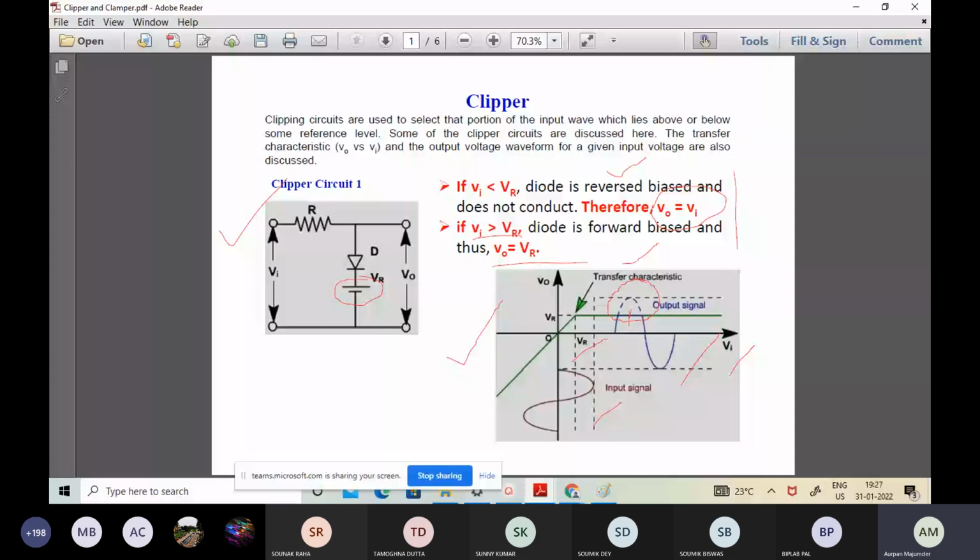The output waveform will get clipped. A similar thing happens practically when you exceed the level of signaling operation in a transistor. So you have to be careful about the level of signal you apply to a common emitter amplifier, because out of the three configurations it gives you the best form of amplification in all respects. So the clipping kind of waveform we can also observe in the context of amplifiers.